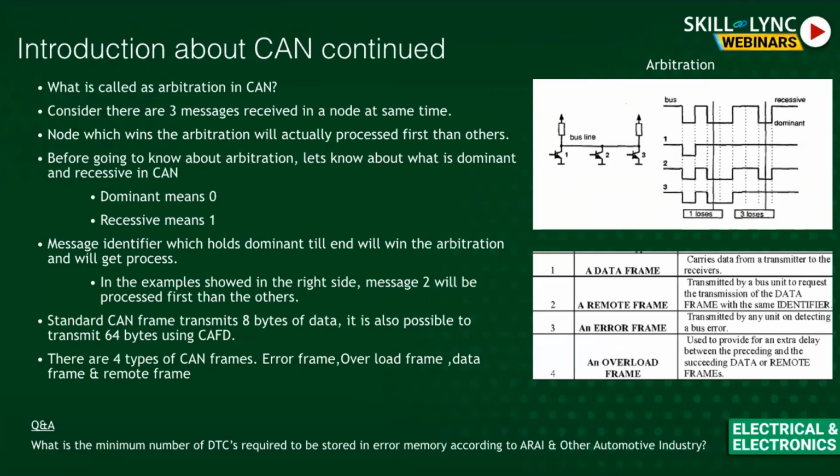Since you are electronics people, you know about TTL logic, right? More than 2.5 volts, I just consider as positive, a 1 bit. If it is less than 2.5 volts, consider it as 0 bit. So it's just a voltage division. If it is more than 2.5, just declare it as a boolean 1. And if less than 2.5 volts is received, then boolean 0. That is how the electrical signals pass through and communicate.